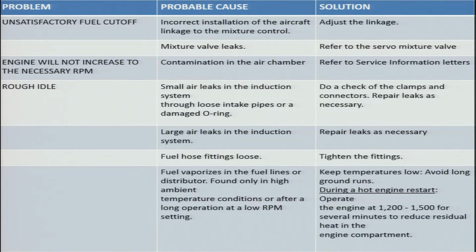This is a very common problem of fuel vaporizing in the fuel lines, especially during hot conditions or when we are operating the engine at low power settings for a long time. So, it is better to keep the temperatures low and avoid long ground runs.